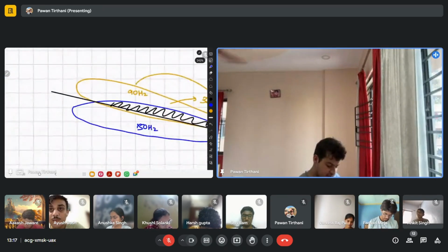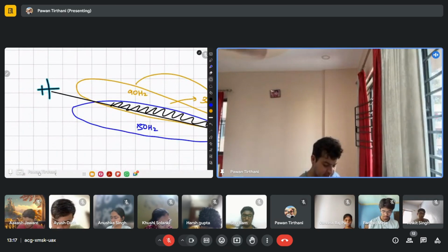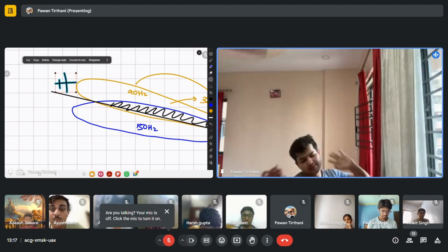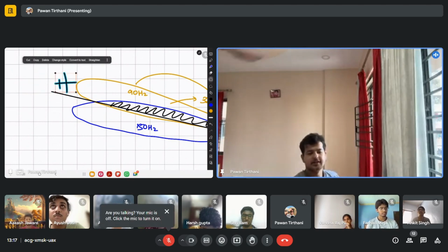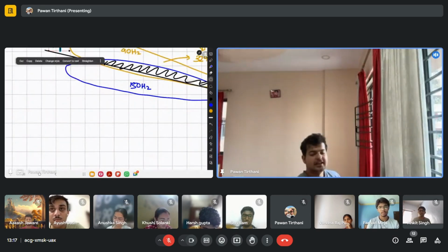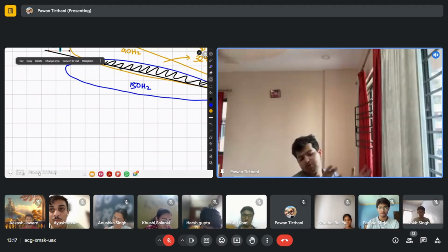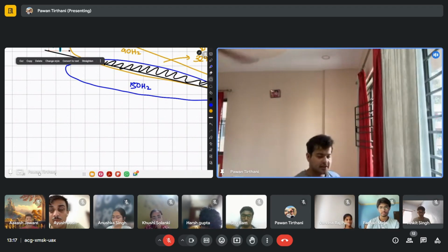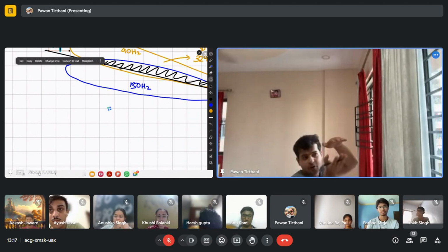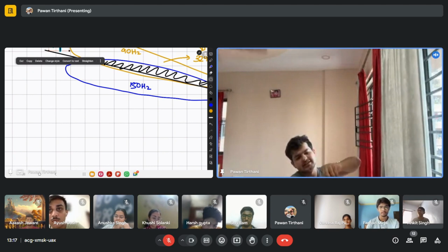how does this work? Let's say there is an aircraft that is coming over here, and he's flying a little bit high. I cannot see anything outside. I just know I want to come to the runway. What will the radio, the receiver, do? The receiver will sense the indication, and he will measure the difference in depth of modulation. Am I receiving more of the 90 hertz modulation and less of 150 hertz? Or am I receiving more of the 150 hertz modulation and less of the 90 hertz modulation?